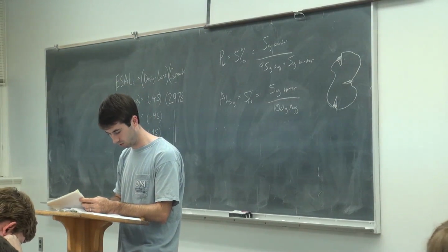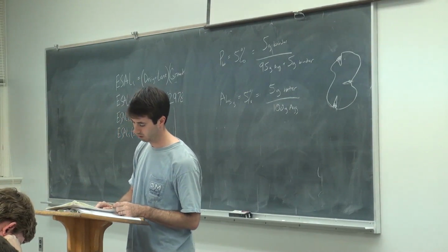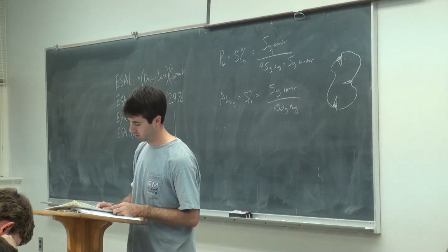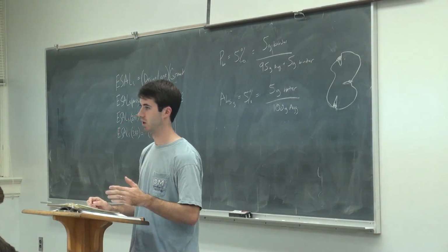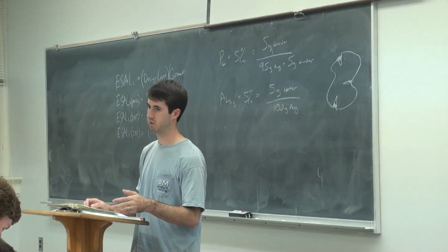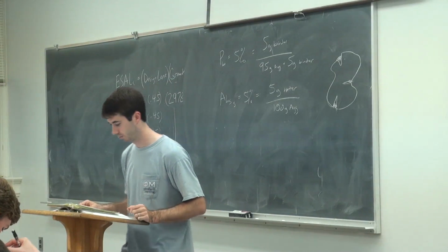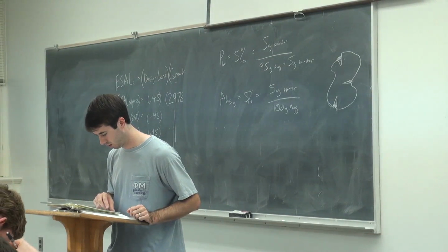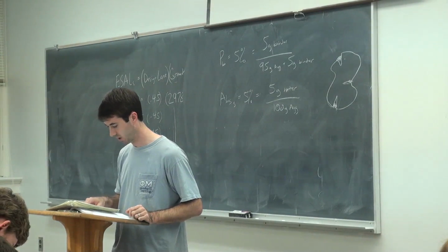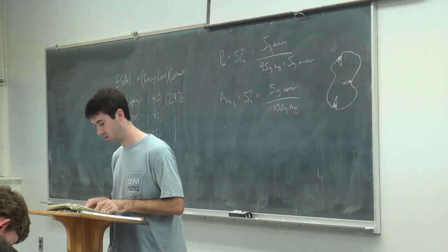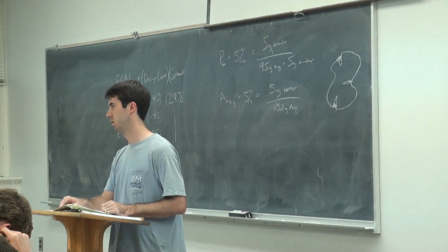So you've got a maximum stiffness of 300 and a minimum m-value of 0.3. You do the same thing where you keep testing until you find the first temperature that it passes at, or the coldest temperature that you can go without failing. So take a look at -12 there. If we pass at -12 and go all the way back up the top, the performance grade is 64-22.